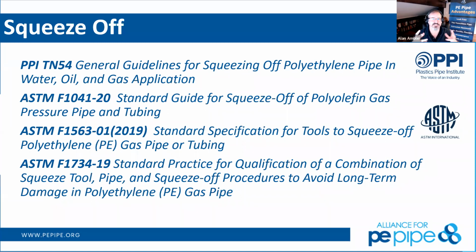So what that typically means within the operation of a municipal water and wastewater system is that the recurring is the pump on, pump off, valve on, valve off, that type of thing that happens as we routinely move water through a charged potable water system. And the occasional surge now becomes the all pumps on, all pumps off. So that's going to be like water main failure when the pumping equipment is actually responding to water moving through the system, or all pumps on, all pumps off, that type of thing that happens when we're doing a firefight or something of that nature.